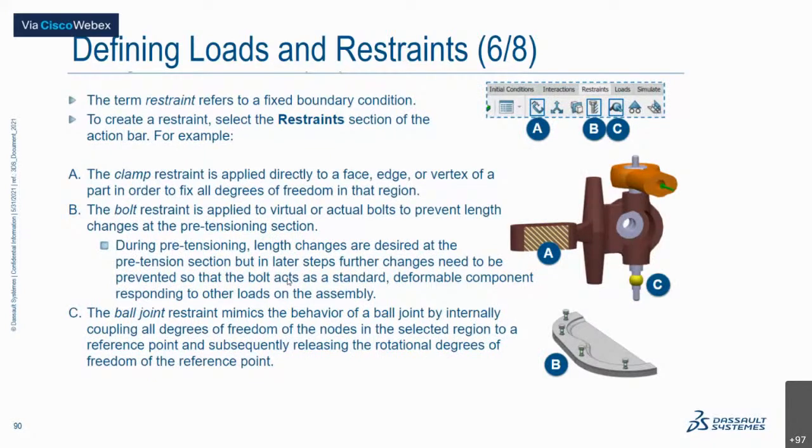Now, once you have defined the loads, that is the forces or the pressures that are acting on your model, you can go on to defining restraints. So restraints are basically defining boundary conditions. A restraint could be anything from a clamp, a fixed displacement, to a bolt load. So it could be anything.